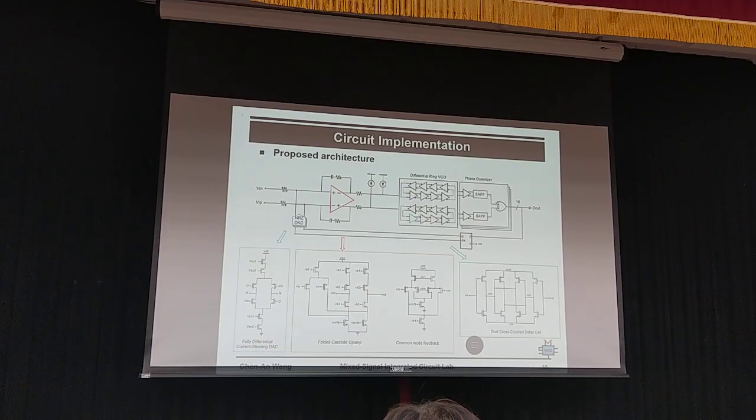Finally, to maintain high energy efficiency and operating speed for the entire system, the feedback path utilizes a fully differential current-steering DAC to implement the non-return-to-zero DAC.